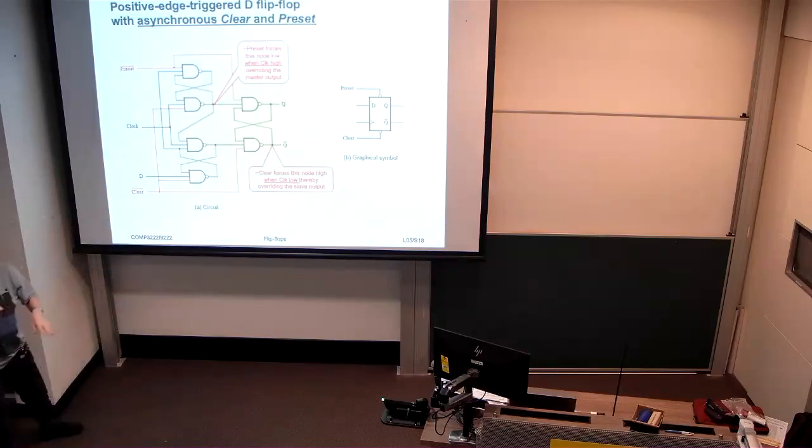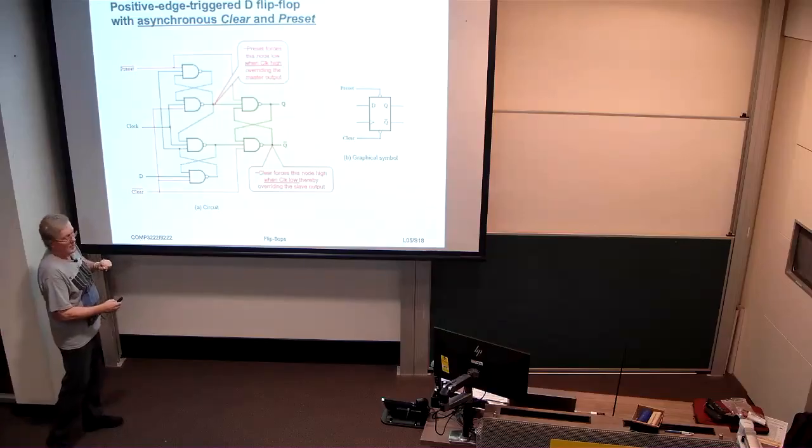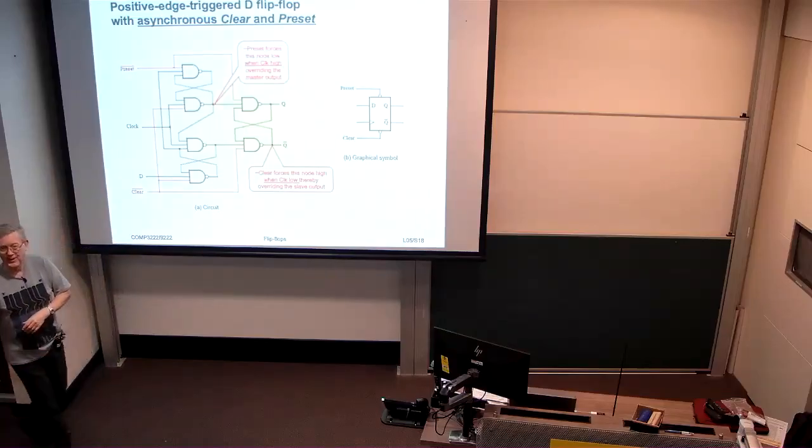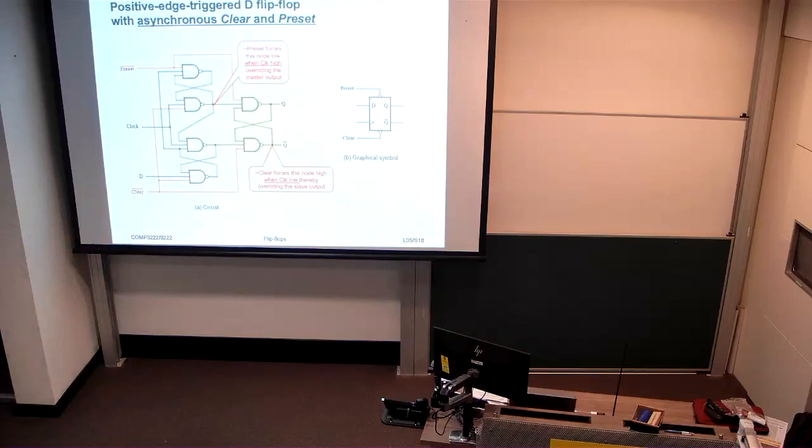So in either the high state or the low state, we're able to clear or preset this flip-flop, and it's a similar argument again as to how long that preset or set state is maintained. It'll be maintained until the next rising clock edge. That will ensure that it's cleared. Okay. Right, are there any questions on this right now? I think I'm probably stretching the limits of what you're able to take in one lecture, but are there any questions you have right now, burning questions?